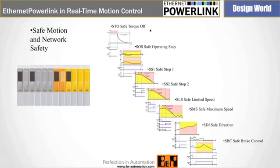Safety as well. There are safe motion devices which can also sit on the PowerLink network, and once again we have safe frames, redundant frames within the PowerLink packages, and obviously from that you can eliminate all your emergency stops, your safety relays, and you can also eliminate all of your light guards and stuff like that wired directly back to safety relays and wiring them directly back to your control system.